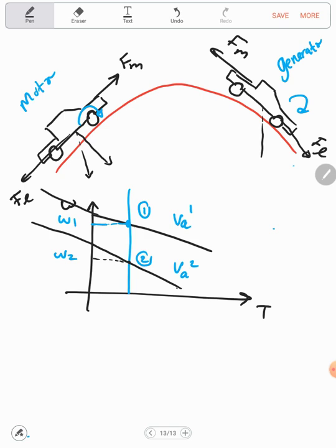And in order to go from 1 to 2, if I change the voltage from 1 to 2, this means that this line now is forbidden, and I should follow this line. So the first thing here, I will go to this point. Do you see now? The load causes the machine to operate at a speed higher than the no load speed in the same direction of rotation. In this case, I'm entering regenerative braking.